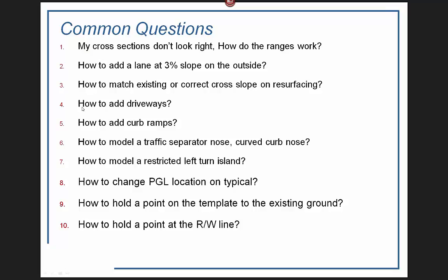In other words, if you have any of these questions, you're just going to have to wait until we do the detailed modeling, and I'll show you how we've got civil cells for a lot of these things. These are sort of appendages to your corridor. You're going to let your template do just a broad swipe through your corridor.